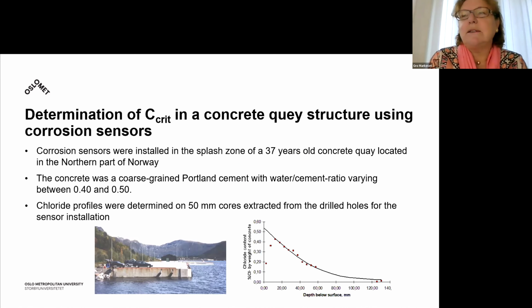So I will go into the investigations, or the determination, of the Ccrit in this quay structure. It is shown below. It's a rather large quay structure in the fjord up in the north of Norway. And in that structure, we installed corrosion sensors in the splash zone. At that time, the structure was 37 years old.